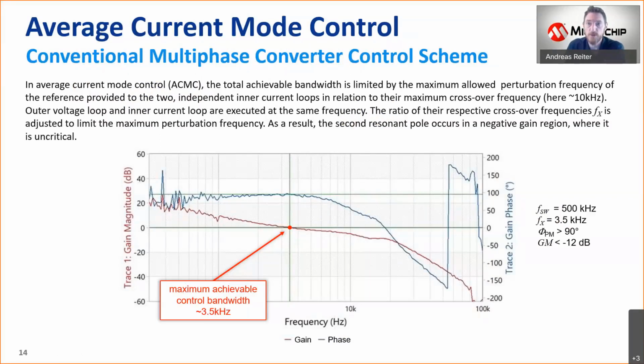But there's also no constant frequency reference input, so the voltage reference will also continuously tweak and change the reference. When you have a control system which is perturbed from two directions, figuring out your safe operating point and stability requires looking at both sides, the input side on the reference and the feedback side.